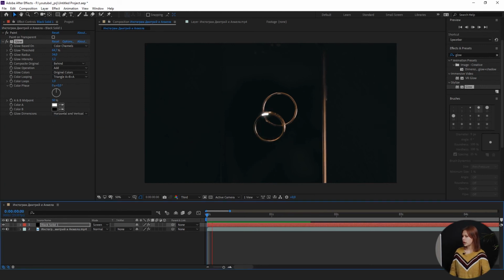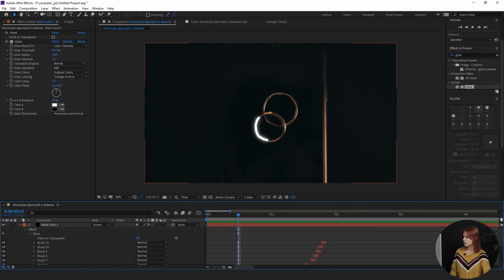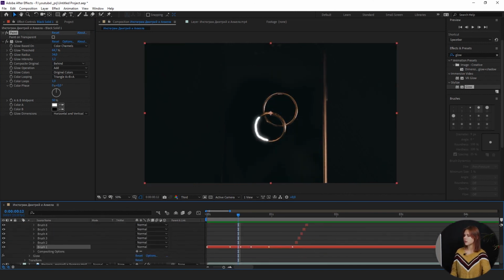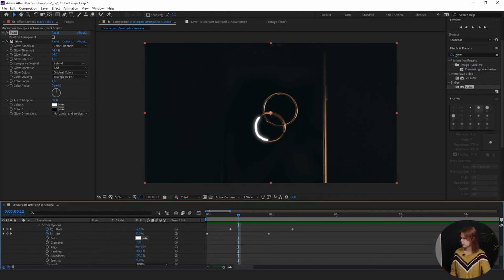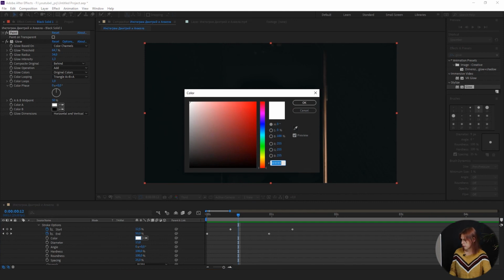If we want to change the color of the lines, we need to open the properties of the transparent layer and find our strokes by opening the stroke options in the Effects tab. Lastly, set the preferred color for the desired line.